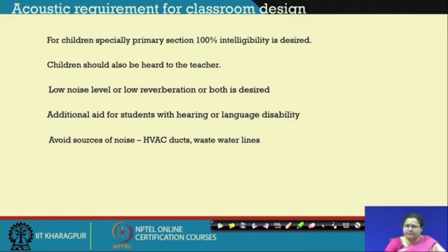You should not keep such architectural elements which are an integral part of the design without planning for them. The rainwater downcomers from the roof, or outlet pipes from the toilets having a wall adjacent to the classroom, such things should be avoided. While designing, you must start by keeping in mind that the classroom should be in a noise free zone, and all the service related noise should be planned in such a way that it is farthest from the classrooms or the set of classrooms.